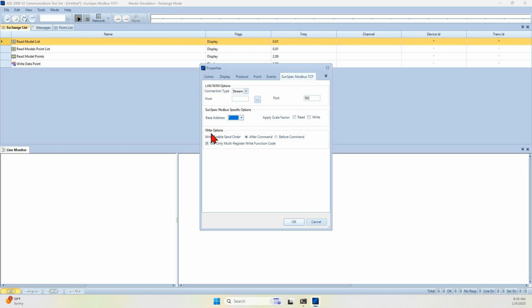Other capabilities are in the case of writes or schedules. So there is an enable feature. That means the data is written into the SunSpec Modbus device, and later there is an additional enable data point that needs to be written to apply that write.